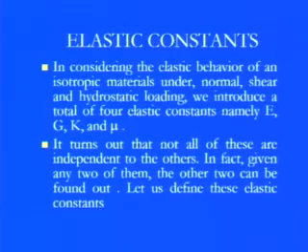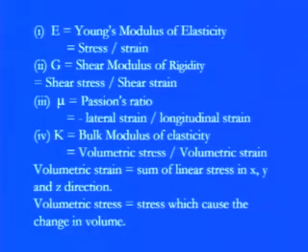So first of all, what is the Young's modulus of elasticity? It always comes from Hooke's law: if the stress is proportional to strain, then if you equate those things, there is a constant, and the constant is known as the Young's modulus of elasticity. So E is nothing but stress by strain.